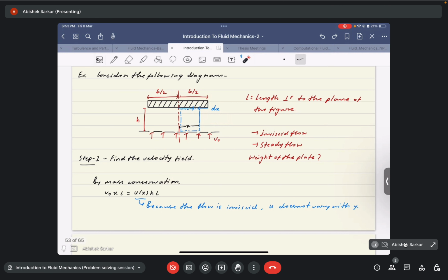More about the control volume we will discuss while discussing the Reynolds transport theorem and the Navier-Stokes equation. There we will see a detailed analysis of the good choices for a control volume, but for the time being you can just understand it as a region that we are focusing upon. It is basically the Eulerian approach, where we mention the control volume, the region of our attention, where we are trying to solve the fluid flow equations.